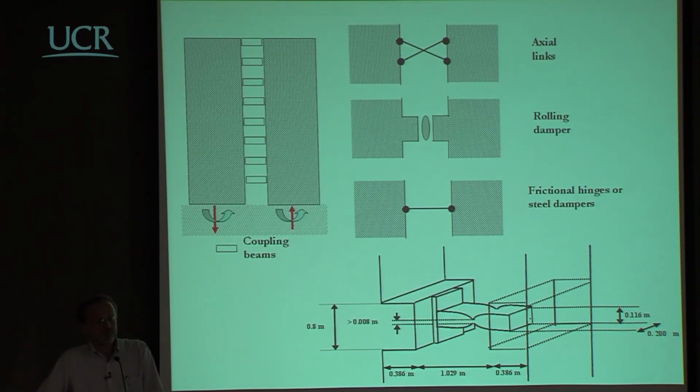Of course, you could do even something more, because in this case, you are assuming to have a plastic hinge here and here, so still have some damage at the base of the walls, but you could design two rocking walls coupled by damping elements, and maybe having some small retaining capacity at the edge, given by some small cable there. And you have designed a structure that has no damage, you control the response, and so on.